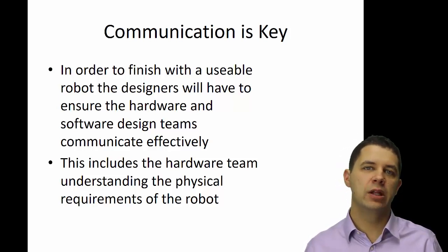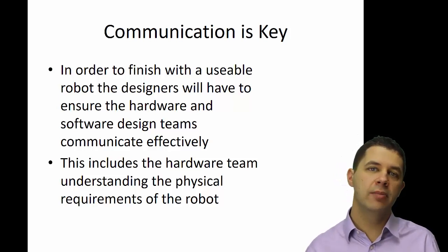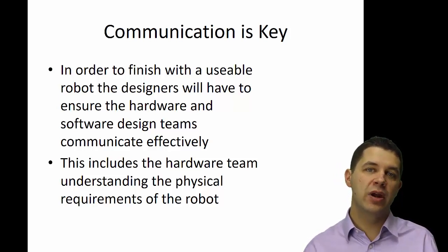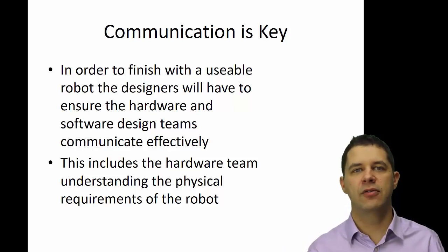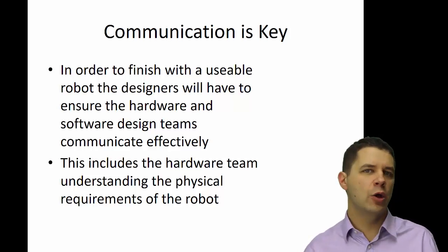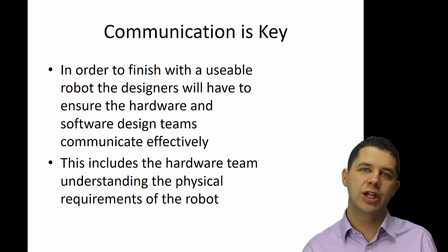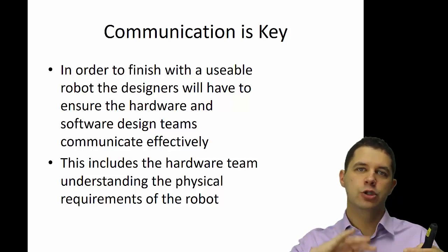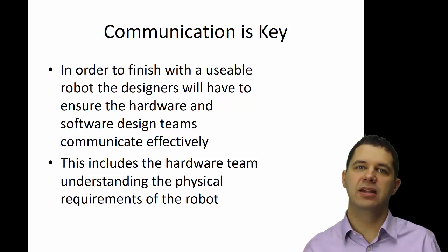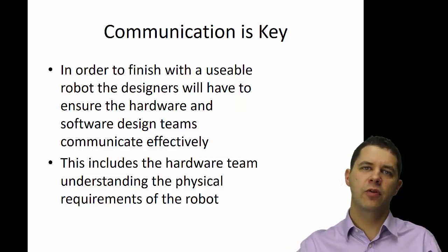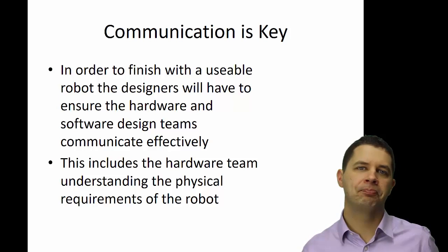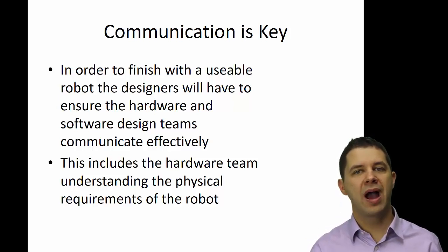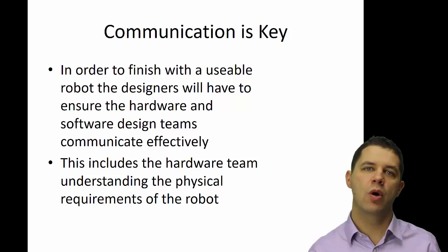One of our students was recently working on a project in Germany at the Fraunhofer, and they were talking about one of the issues between the hardware and the software that they were designing, which was endianness. This is a concept I cover in digital electronics and controllers, but it's the byte or bit order that we're actually storing or transmitting our data in. And they needed to write a function to convert it over. They realized after a little while that the data seemed garbled when it was coming out, and once they converted it over and reversed the endianness from big endian to little endian, it worked perfectly fine.